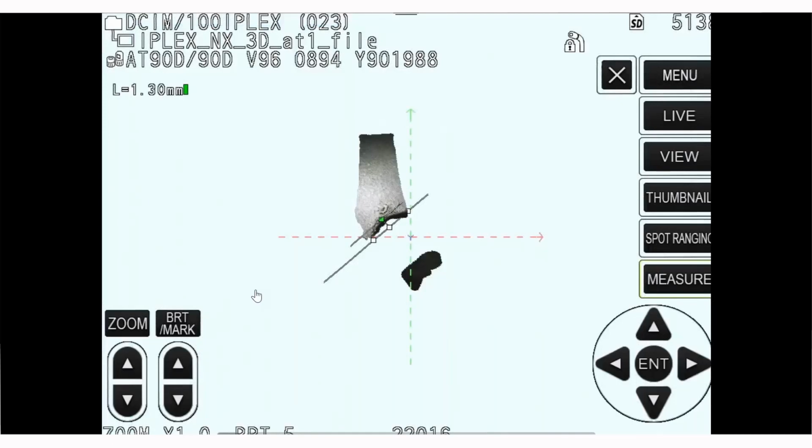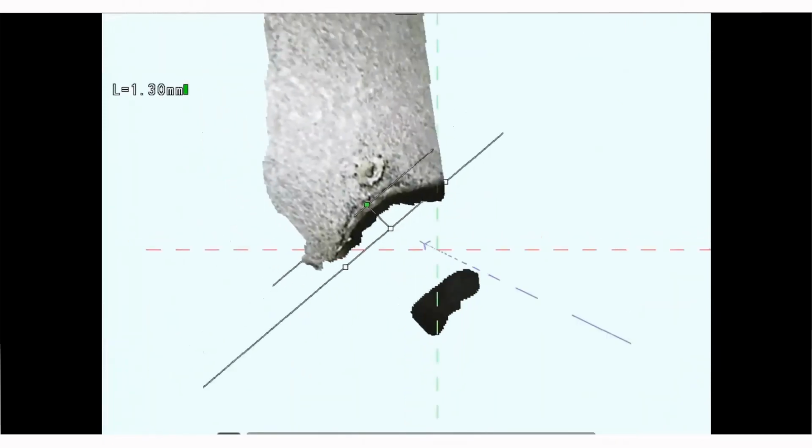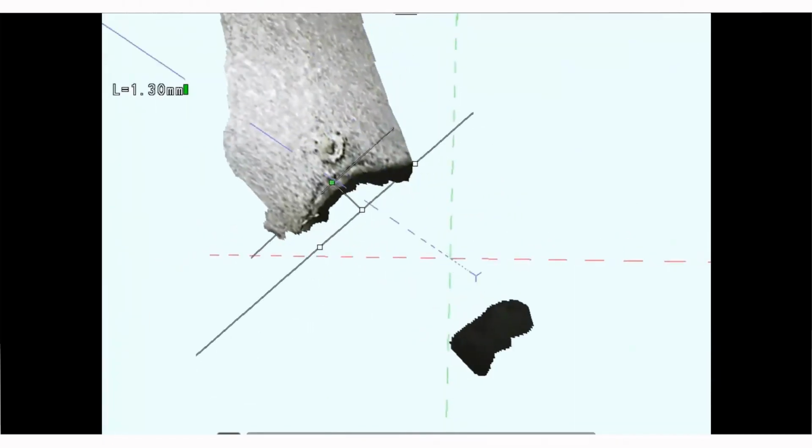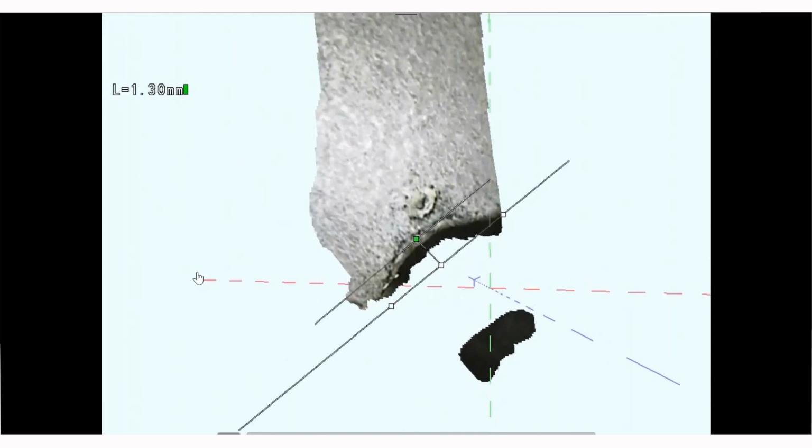Now when we see it on the 3D model, what we see is that the reference line is actually completely out, it's away from our blade. So these points here should be much closer to the blade. So what I'm seeing here is, although on the image it looks like the points are in the right place, the 3D model showed me that they are not. And this might be the difference between rejecting or keeping an engine on the wing.